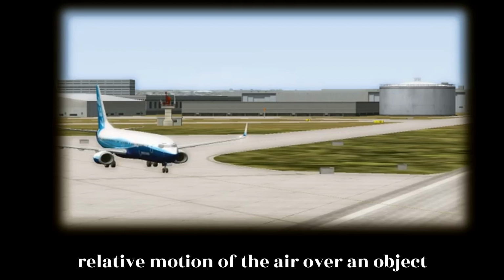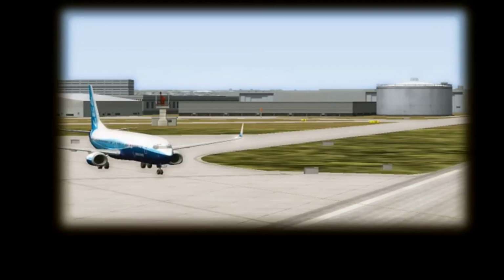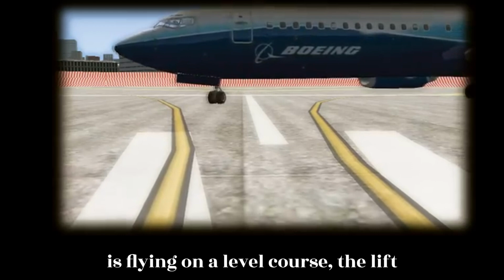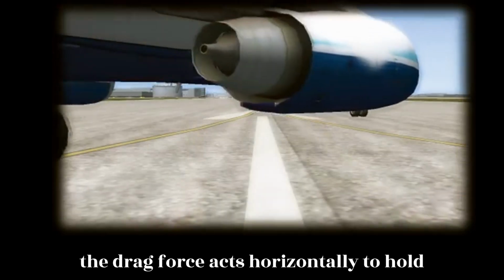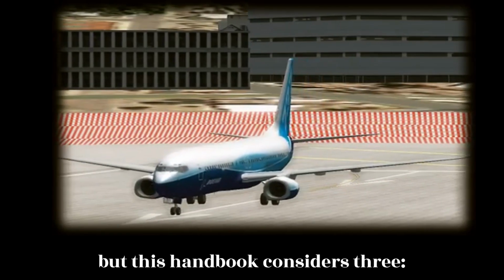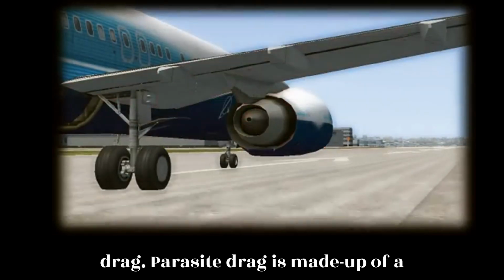The relative motion of the air over an object that produces lift also produces drag. Drag is the resistance of the air to objects moving through it. If an aircraft is flying on a level course, the lift force acts vertically to support it while the drag force acts horizontally to hold it back. The total amount of drag on an aircraft is made up of many drag forces, but this handbook considers three: parasite drag, profile drag, and induced drag.